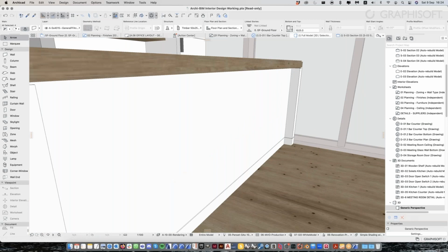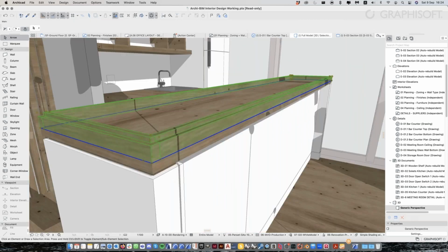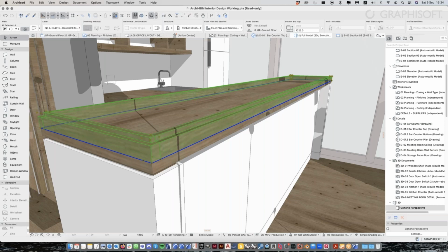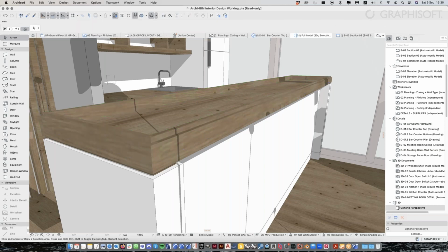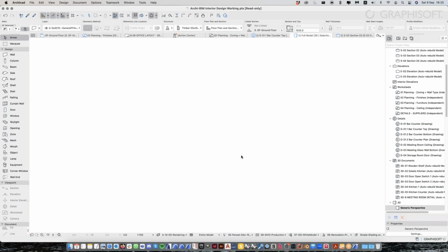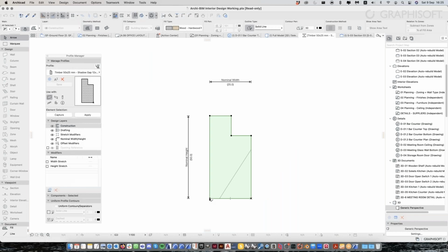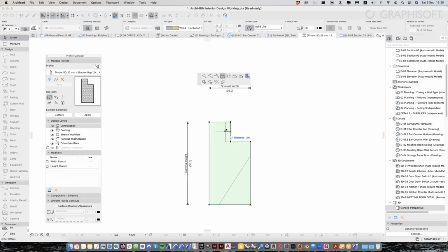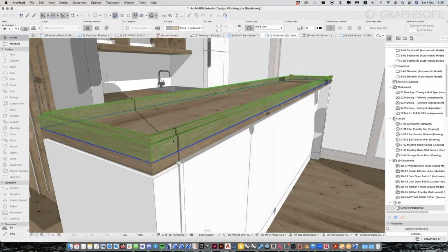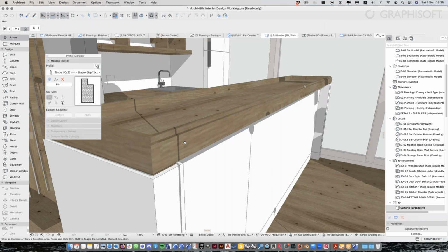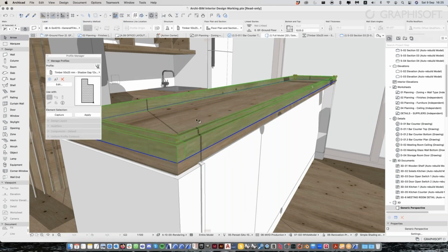That is a wall. So if I open this, I used a very simple profile, this piece. The reference line is here, and then I just use a wall. So this was the shape of the profile. Good thing is if I do this, then I can feel free to adjust that gap, it can be bigger, smaller. And once I update this profile, then all the gaps will be updated as well. Okay, and then again, a slab.